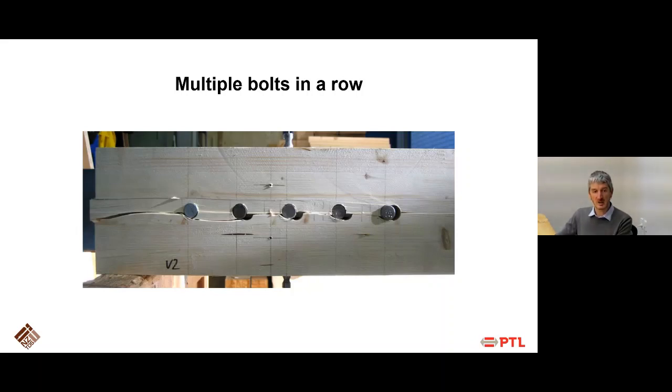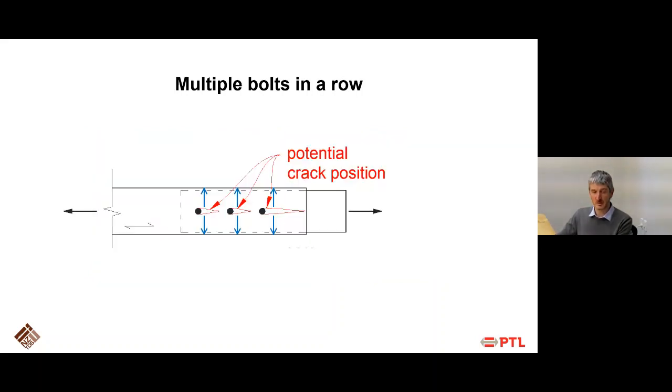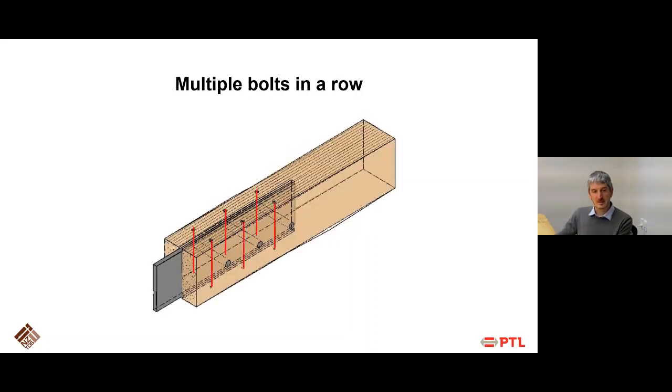You can again rely on the equations in the new timber design standard to do so. If you fail the test, you can also prevent this from happening by providing reinforcing. The idea here is again to make sure that the forces created by the timber trying to pull the timber apart, that there's actually a load path for them. This is a typical scenario with a slotted steel plate with 3 bolts or dowels, and by using fully threaded screws, you can make sure that these bolts don't have the ability to open up or to split the timber open.